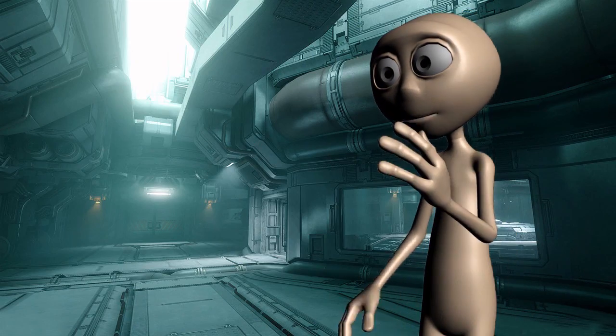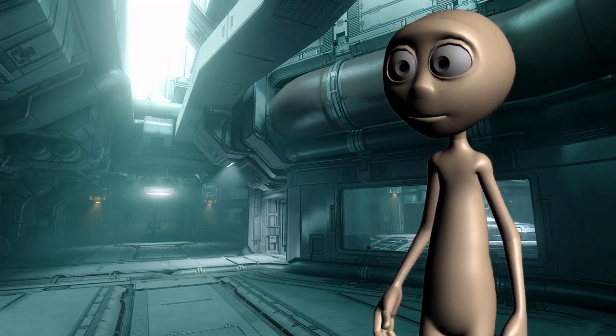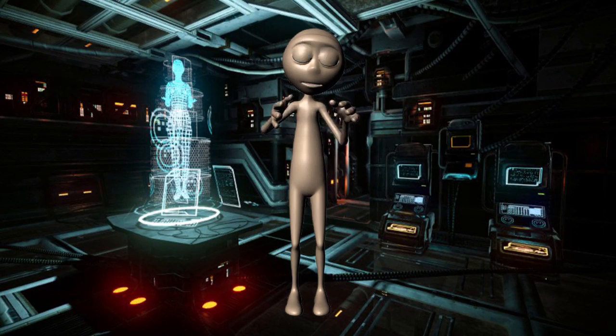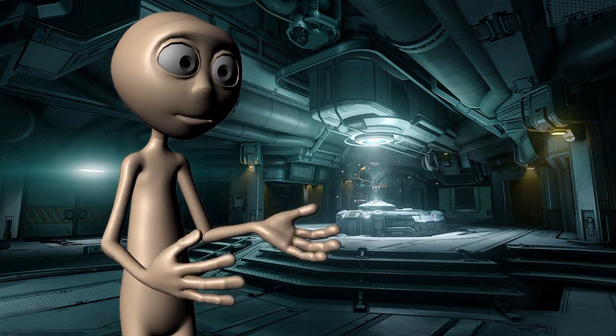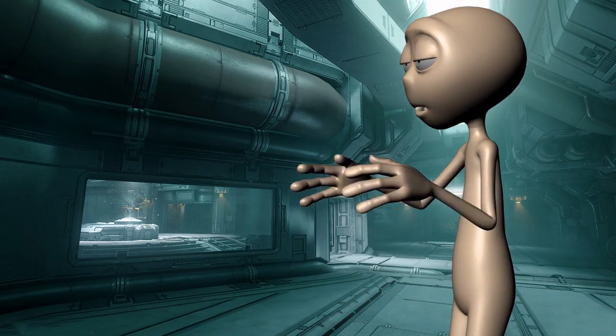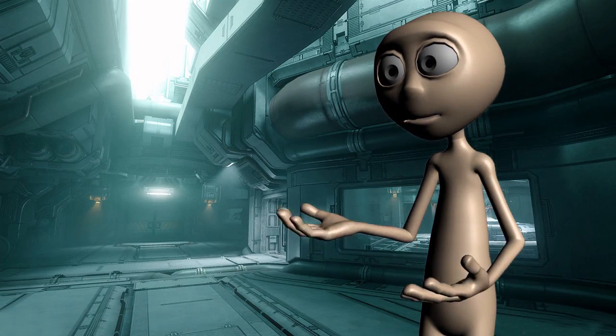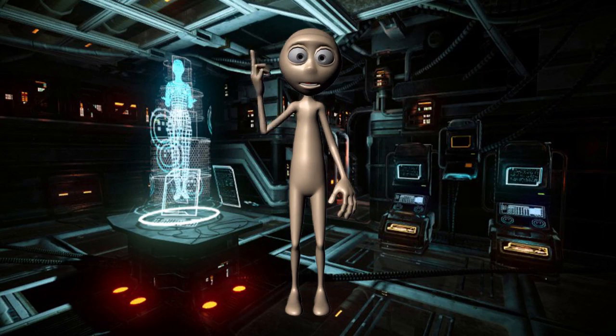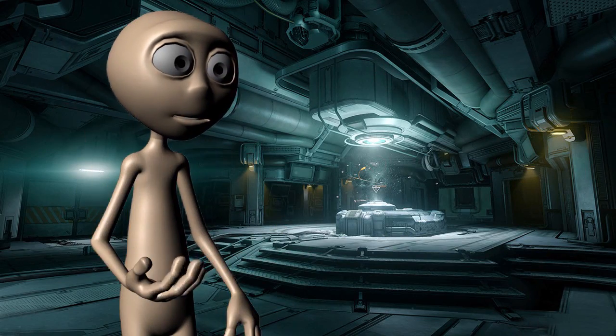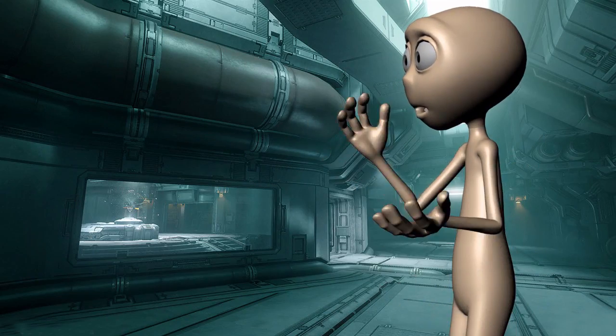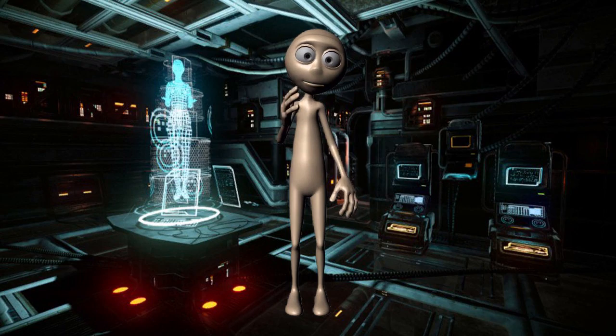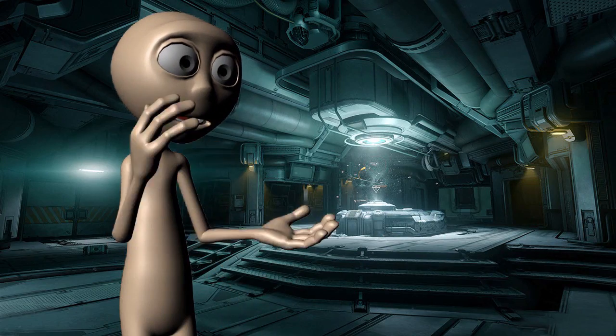And Chatur again has to say some advantages as well as some disadvantages for it. The advantages are, it is an accurate method to find shear capacity. It resembles the field conditions. The soil is free to fail in the weakest plane. Precise measurement of pore pressure and volume change is possible. Complete control over the drainage conditions. And the state of stress in the specimen during any stage of the test is determined.